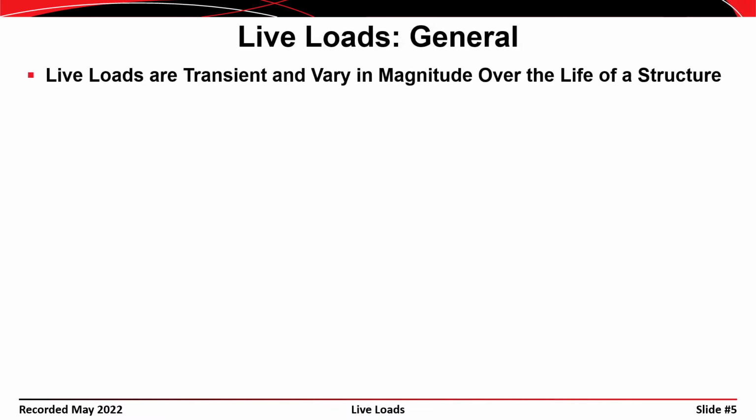Live loads are transient in nature and can vary over the life of the structure. That makes them fundamentally different than dead loads. Dead loads are permanent loads and they're assumed to always be present on the structure, but live loads are not. They're different.